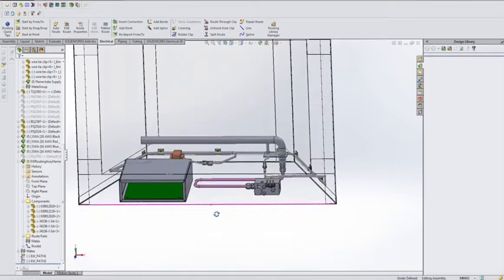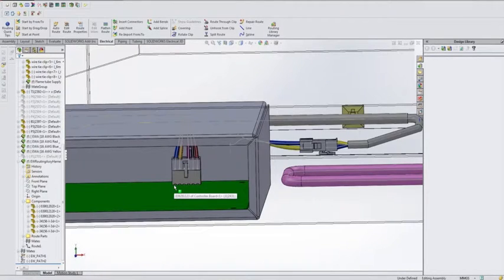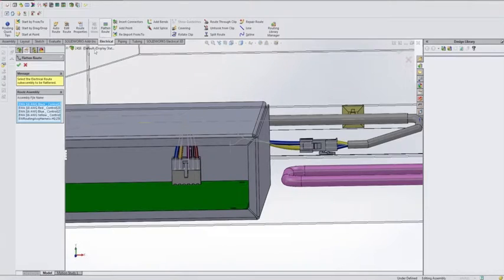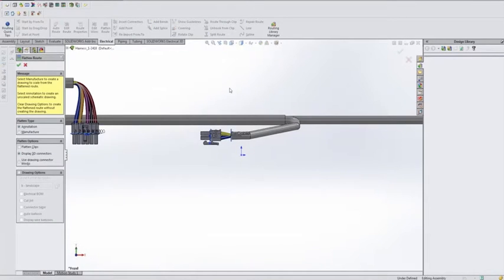Once we have this set up, right, this gives us our lengths already. We can go back to our SOLIDWORKS Electrical 2D and give us our reports. But if we want a nice, clean way to view this and send it out to manufacturing, for example, right, we can also flatten this out. So by going to flatten route, right, I can indicate once again my harness. I'll go ahead and press OK. And I'll click Yes to rebuild.